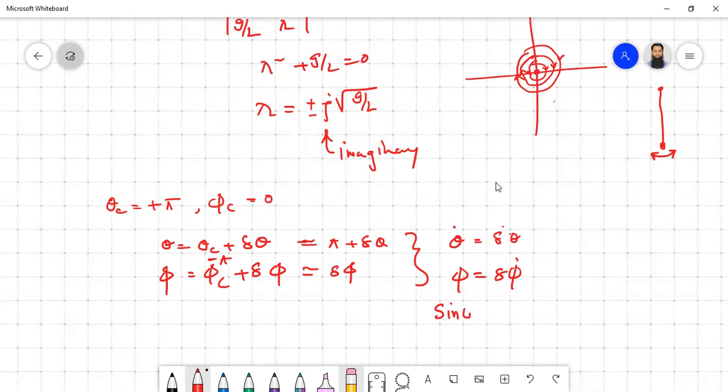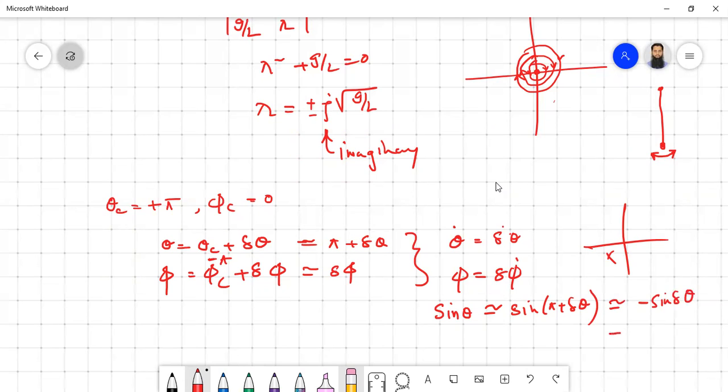Now also the nonlinear term we have to consider. Sin theta is now sin of pi plus del theta. So now we are in this coordinate somewhere here, where sine is negative, so it will be just minus sine del theta. And we know that in the linear model from the Taylor series expansion, sine theta equals theta. So basically minus del theta will be the case.